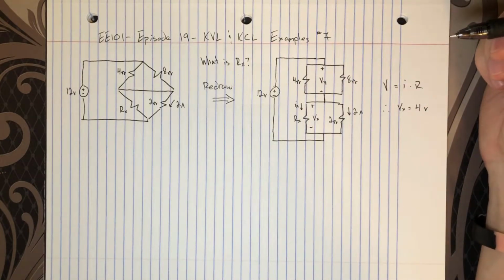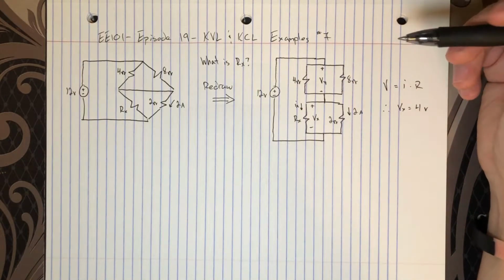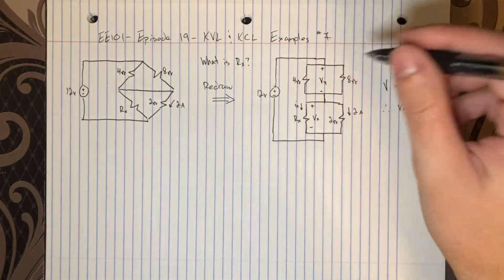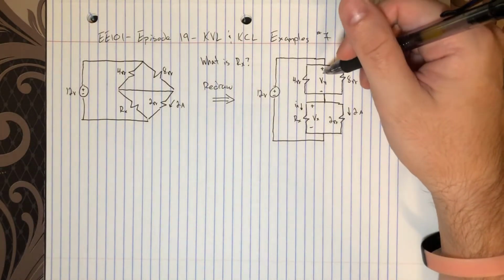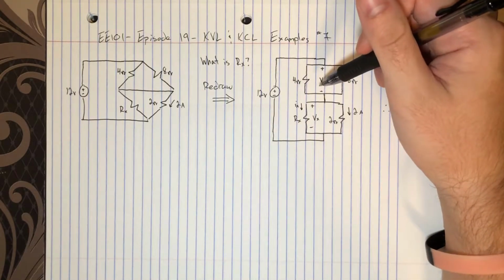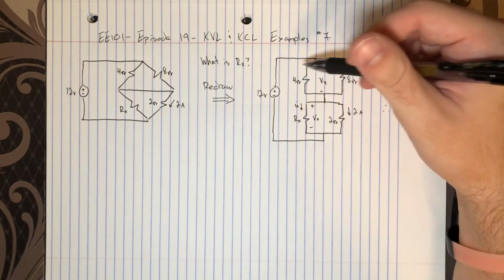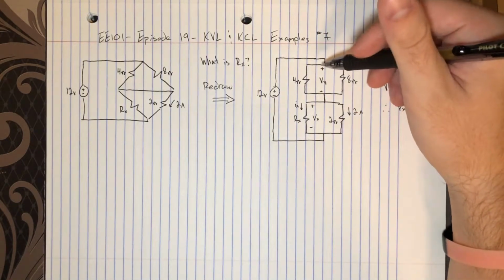And that's a really good way to look at things when you're talking about series versus parallel: look at how many voltages you have in this loop, or how many currents you have in this node. And so in this case, we can easily write a KVL where we step up this 12 volts, and these are all resistors, so we know they're stepping down.